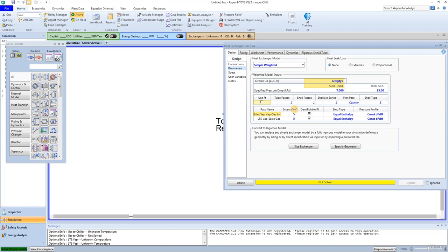In order to arrive at a unique solution, the number of constraints must equal the number of unknown variables. To solve for the unknown product temperatures in the gas-gas exchanger, 2 design constraints are needed. You will use the heat exchanger balance between hot and cold sides. This is a default, and the minimum approach temperature specification.